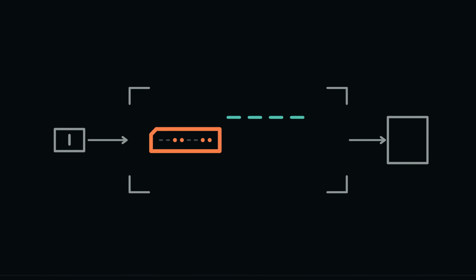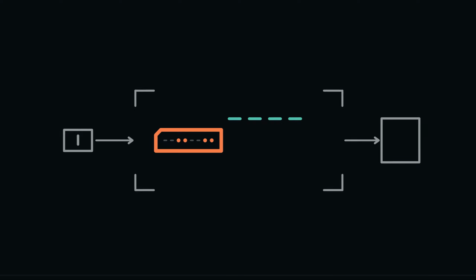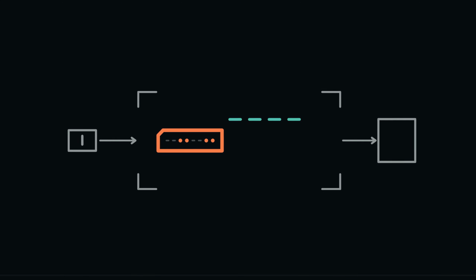Place 8 byte registers beside the shared bus. A data value can now reach the neighborhood, but enabling every register would overwrite all 8 with the same byte. The machine needs a compact way to choose exactly one. An address is a pattern used for that selection. It is not the content stored at the destination.